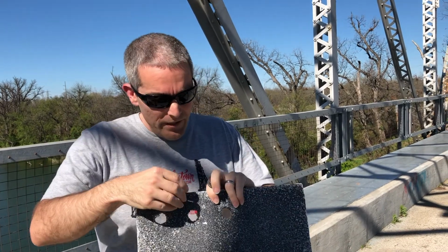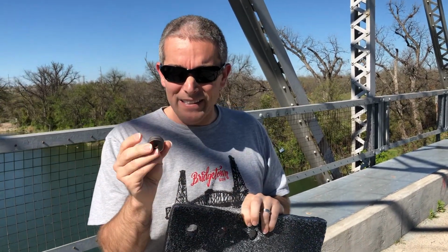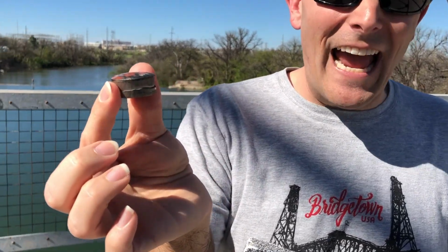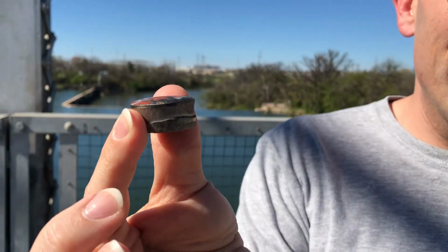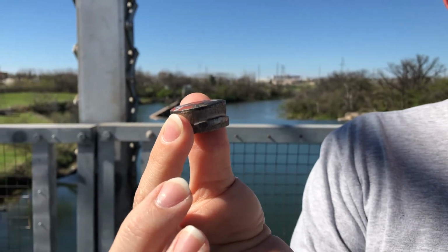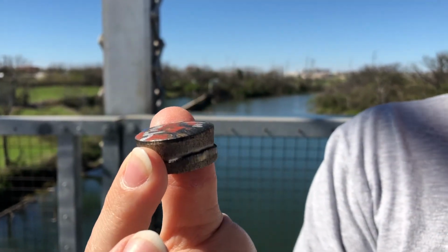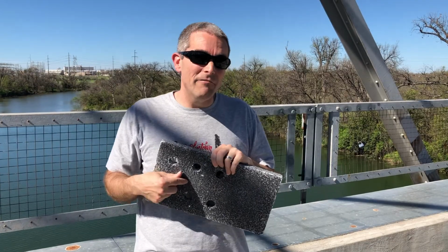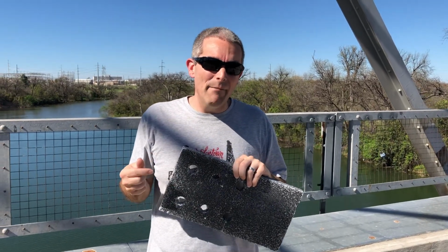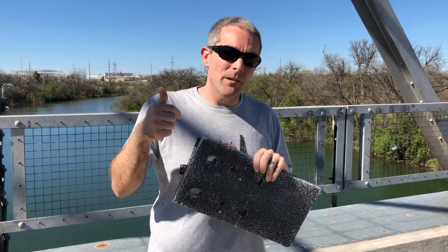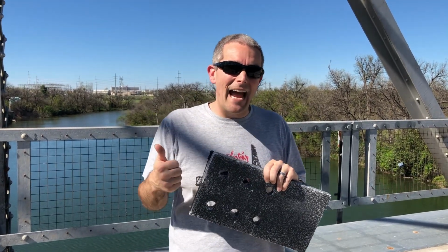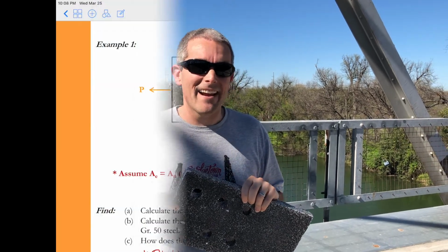And so that's what we're going to do. But when we do that, we get something that looks like this. This is a 1-inch punch. And you can see that there's a lot of damage that occurs on that surface. And so because of that damage, we add an extra 1/16 inch to the effective diameter of the bolt that we need to use for design. So that's why for fracture, we use the diameter of the bolt plus a 1/16 inch for the hole diameter plus a 1/16 inch of damage. That gives us the diameter of the bolt plus 1/8 of an inch.